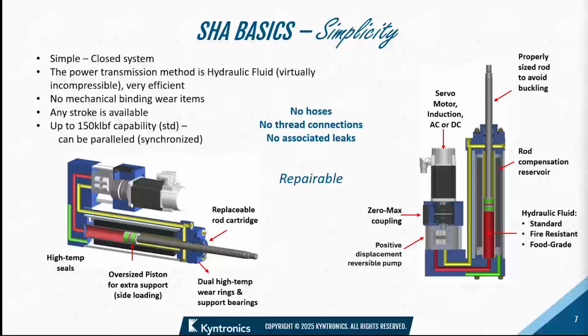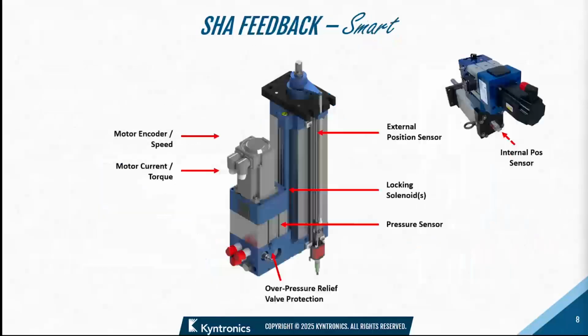As I mentioned, as opposed to the electromechanical, where if something happens to it, you have to throw it away, with our solution, you have to replace some seals. Even if you send it back to us, we can update the seals, etc., and you'll have just like a brand new unit ready to go. So you don't have to throw the actuator away. If you spend the money on the actuator, it's yours and it can be repaired. So it's a smart actuator, and we'll get into using these feedback devices in a little bit.